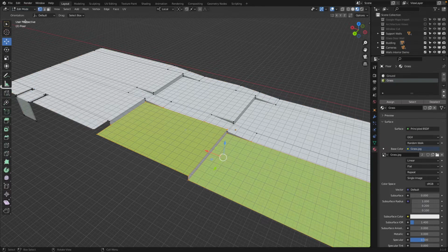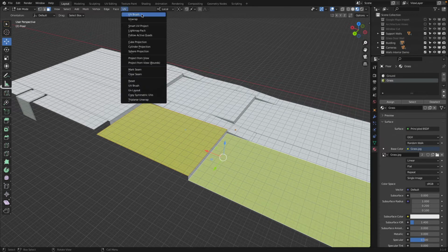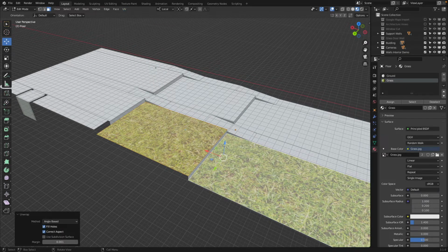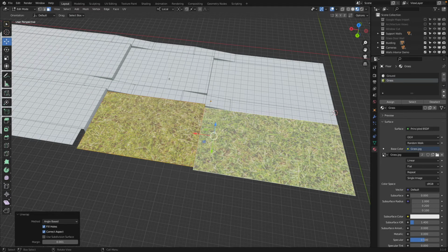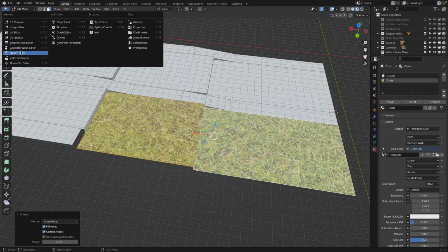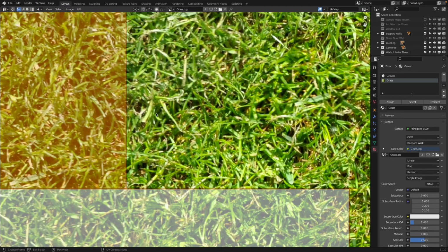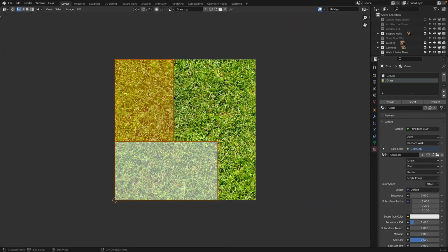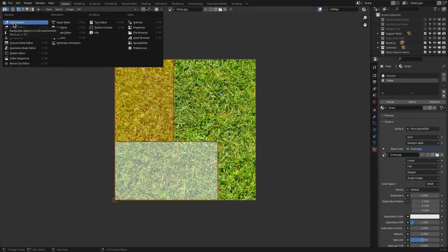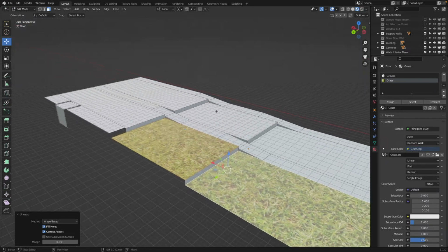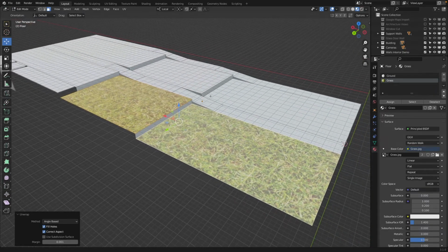It's very easy. In edit mode, select the two faces, and then we go to UV and say unwrap. And that's it. So unwrap, what magically happened? Let me go to UV editor, and there you see these two faces. It created an unwrapped version for it. We will go to this in a moment one more time. Okay, very good. So that wasn't too complicated.